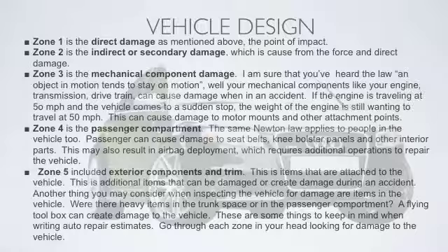If you had a toolbox in the trunk, that could cause some damage inside of there. So there's really more things to look for than the point of impact. If you just look at the direct damage, you're going to be missing quite a bit. So again, I don't want to get too in depth at this point, but these are just some of the things to think about as you start developing a repair plan.